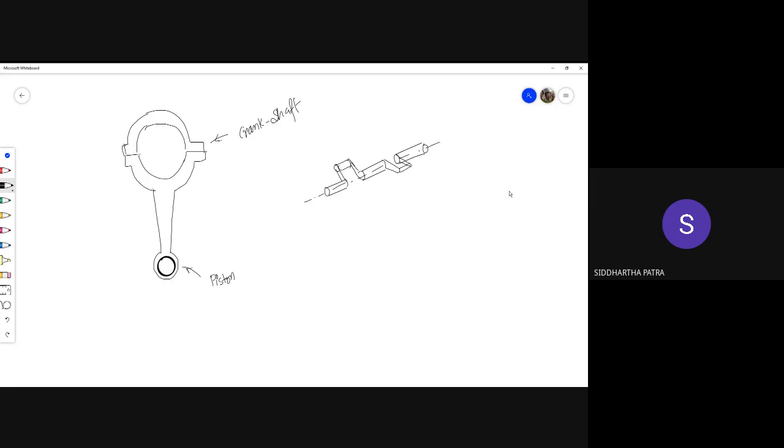In a 2D drawing, it is very easy to show that there is this motor to which this crank is attached. But in practice, if you want to have multiple cranks on a single shaft, or even a single crank on the shaft which is not at one of the ends of the shaft but in the middle, that crank intersects with the shaft axis. And how do you make that? You make that by making the shaft physically non-existent in the portion where there is the crank. So this is what is a crankshaft, and to this cylindrical portion attaches this larger diameter portion of the connecting rod.